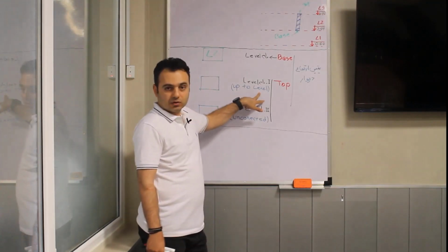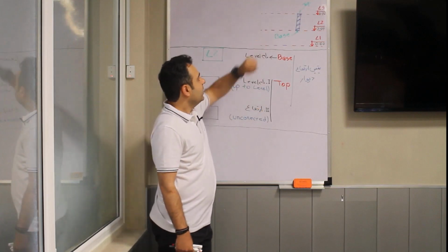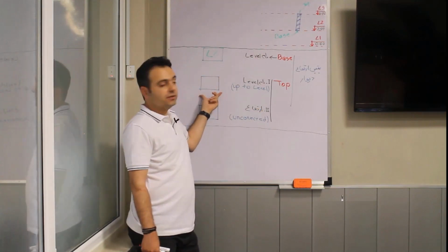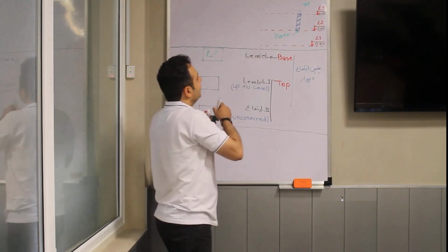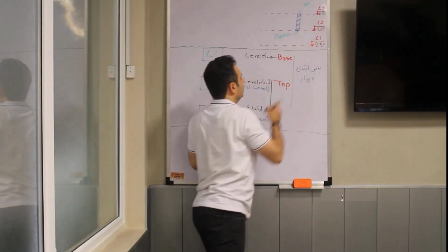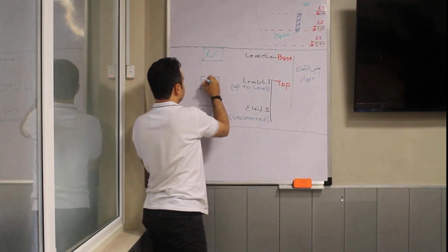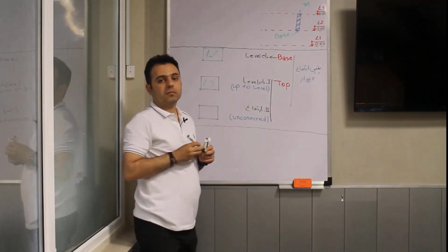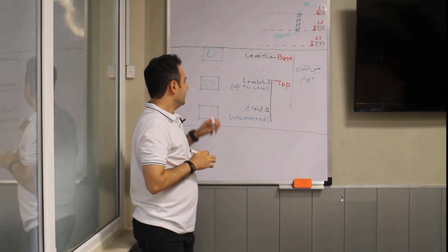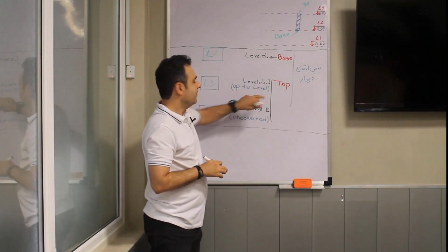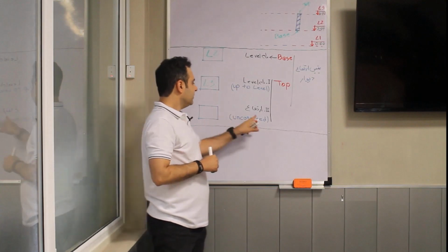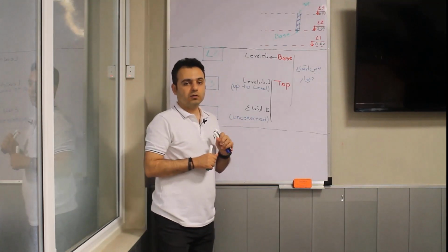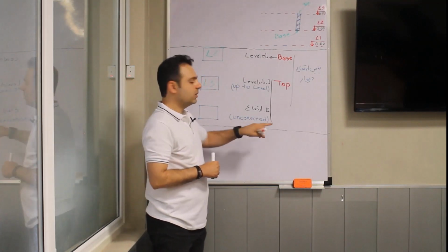If we want to use the up to level method and determine the top of this wall, what should we write down here? I bet you do. That's right, we should write the name of the level on the top, which is L3. Alright, so we say up to level 3. Up to level 3. But the next way is height, that we call the unconnected.